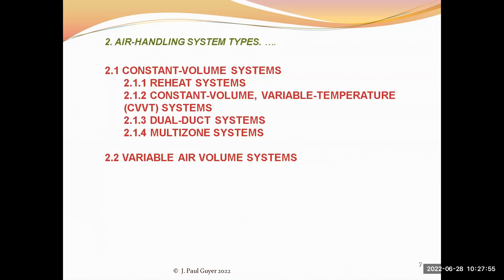In any event, there's some kind of a control sensor that senses that we don't need as much cooling in the building or on this floor, and therefore we will allow the chilled water to be a little warmer before it enters the chilled water coil in the air handler.